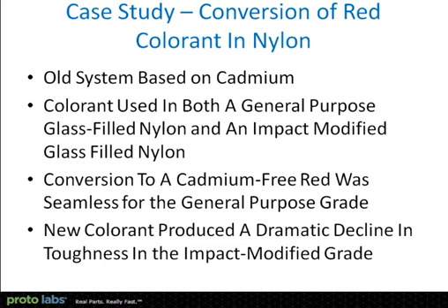And then we took the same technology and put it into an impact-modified glass-filled nylon, and we lost all of our impact resistance for reasons that we never really determined. A lot of times these mechanisms remain a mystery because no one has the time to really dig into the root causes. But the bottom line is this is an application that required very good impact, which is why we were using an impact-modified material in the first place. And when we put this red color in, we lost all that impact strength.